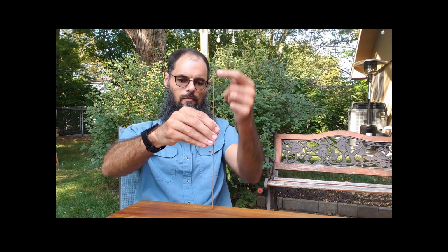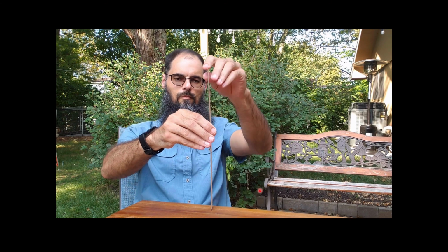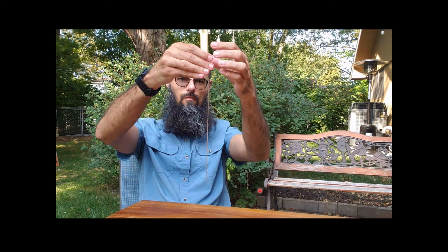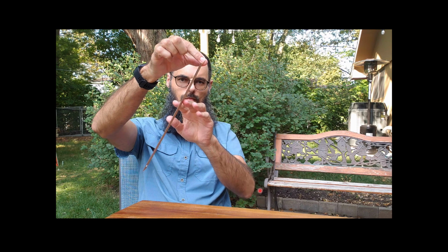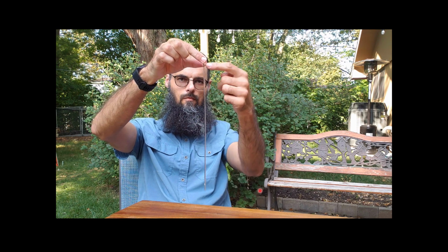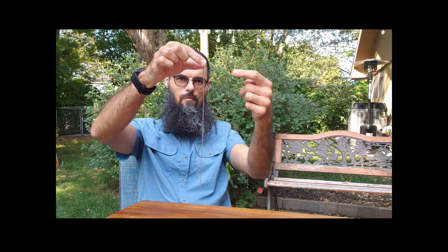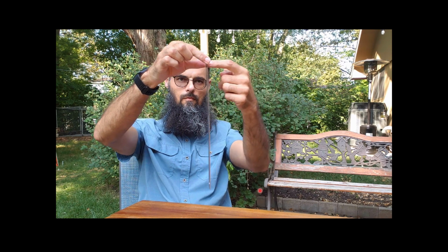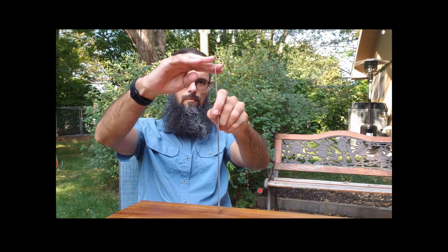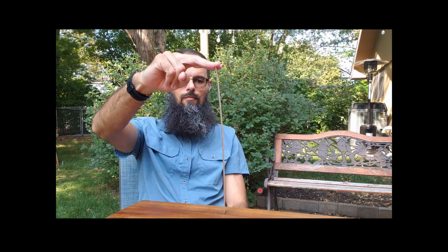At the end of the video here, I had a look at what happens if we have a pin joint at the bottom, but what if there's nothing constraining the top? What if there's no translational constraint, no rotational constraint, and I still try to apply a force at the top? Imagine trying to balance a weight at the top. If it's not perfectly balanced, it's just going to fall over. So this is not a stable, or the pin-free set of boundary conditions.